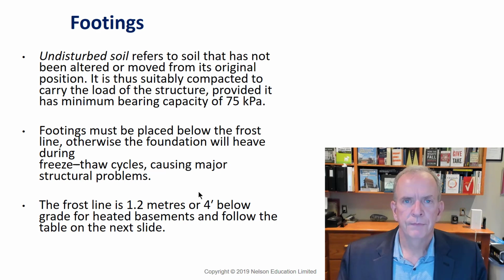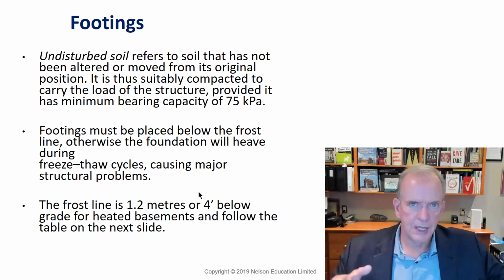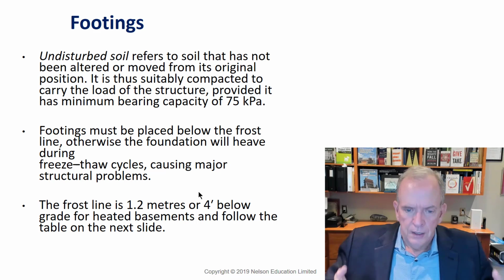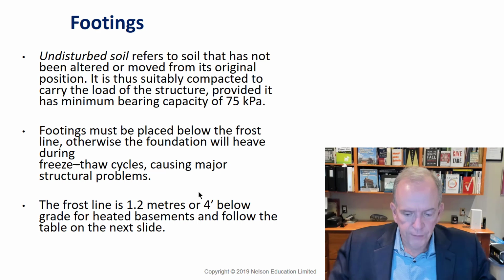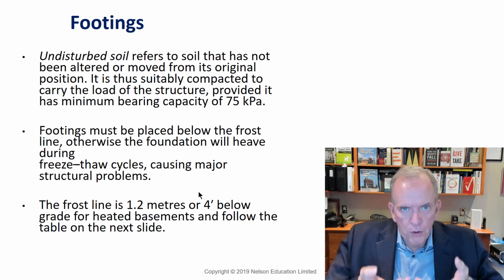If you've ever seen fence posts around the city, where one's up and one's this and one's that, what happens is they weren't down 4 feet. They were maybe down 3 feet. And you have some cold winters and the frost goes down below 3 feet. It heaves the post up.